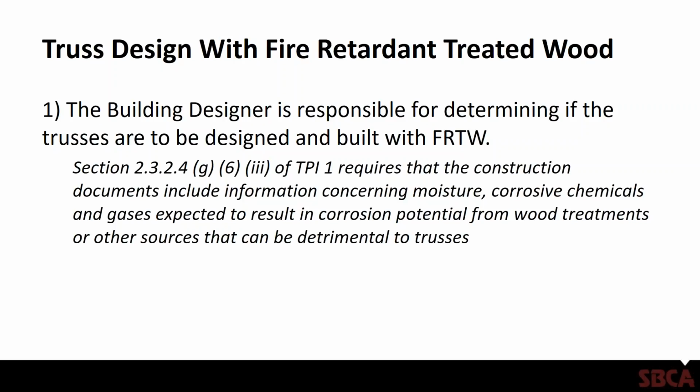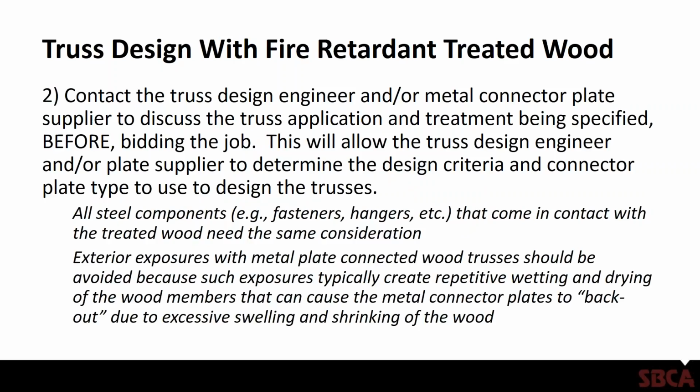So, assuming that information is included in the construction documents, then typically the recommendation is that the truss manufacturer and their design department would contact the truss design engineer and/or the metal connector plate supplier, who typically is the one whose design software they're using.